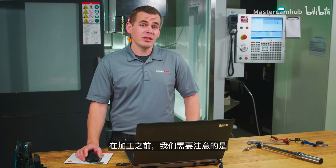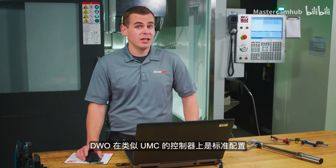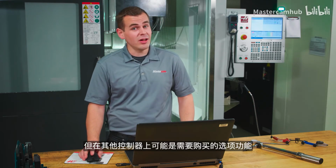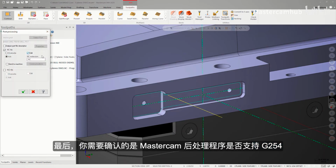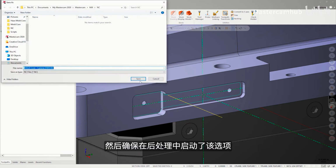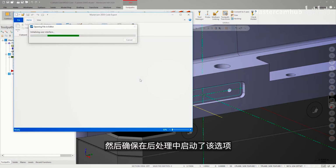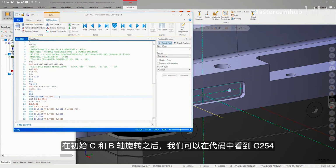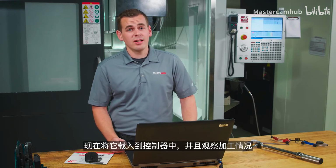Before we head over to the machine, it's important to note that DWO is an option that needs to be enabled on your next-gen control. DWO comes standard on machines like this UMC, but is an optional purchase on other machines. Lastly, you need to make sure your Mastercam post-processor supports G254. So make sure to verify with your post-processor provider that this option is enabled and configured in your post. Once we post out the code, we can see the G254 following the initial C and B axis rotations. Let's load it on the control and see this cut in action.